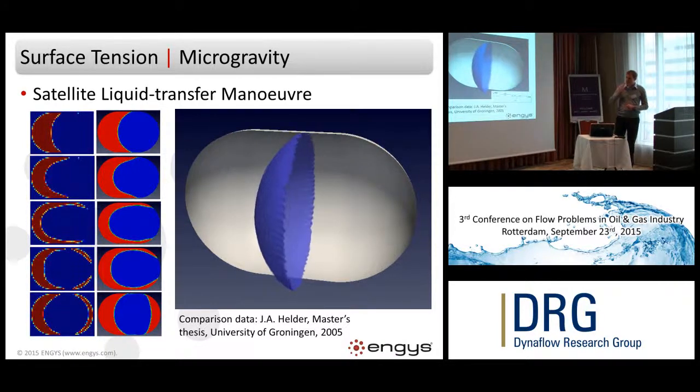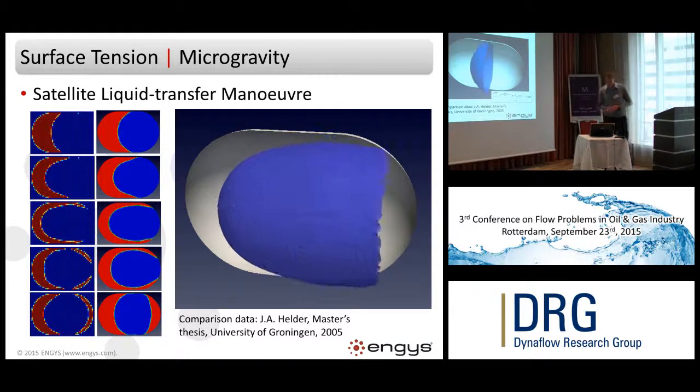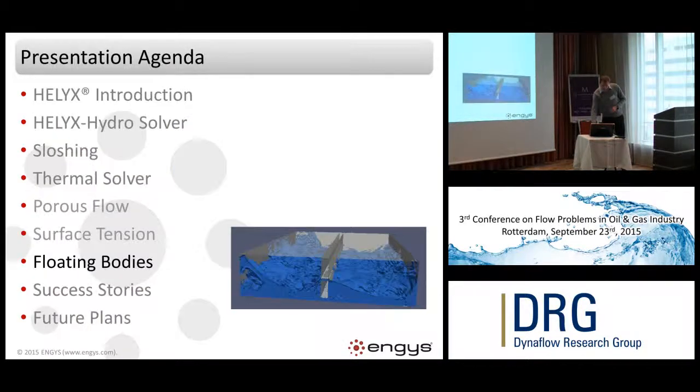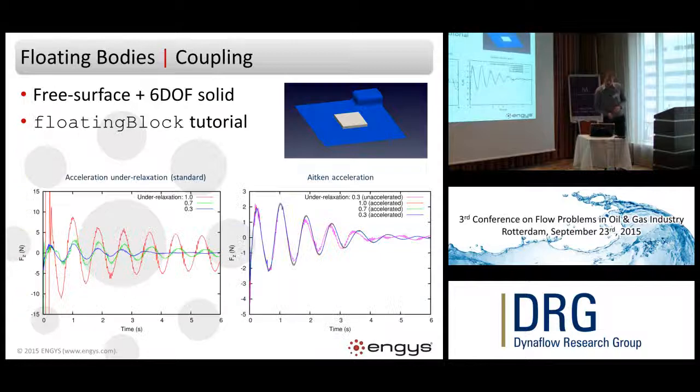It just used purely castellated structured meshes, as you see on the left, but nonetheless got a reasonable correlation between the two codes. Then a few other enhancements that we've made to the handling of coupling between the multi two-phase solver and a 6 degree of freedom solid body.